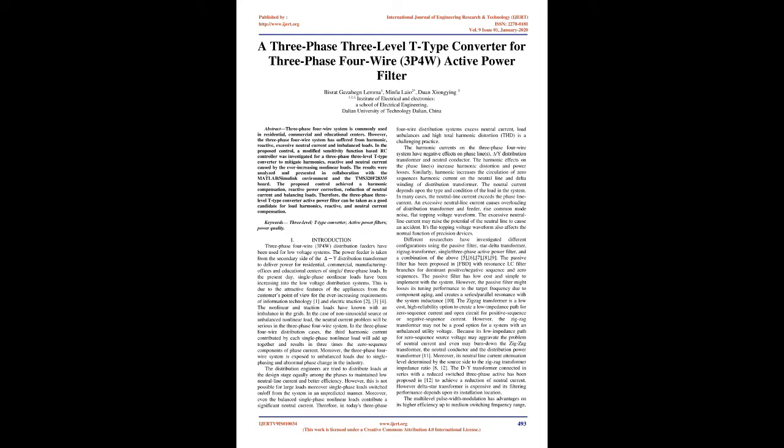In the proposed control, a modified sensitivity function-based RC controller was investigated for a 3-phase 3-level T-type converter to mitigate harmonics, reactive and neutral current caused by the ever-increasing nonlinear loads. The results were analyzed and presented in collaboration with the MATLAB/Simulink environment and the TMS320F28335 board. The proposed control achieved harmonic compensation, reactive power correction, reduction of neutral current, and balancing of loads.